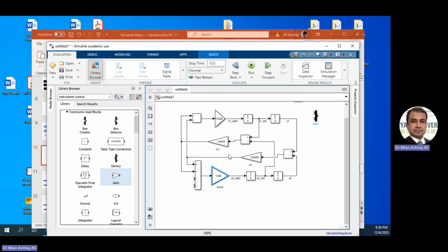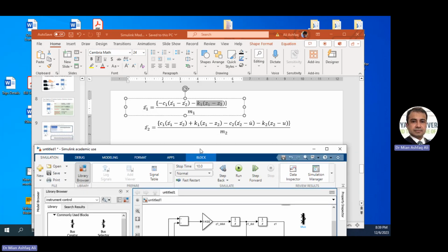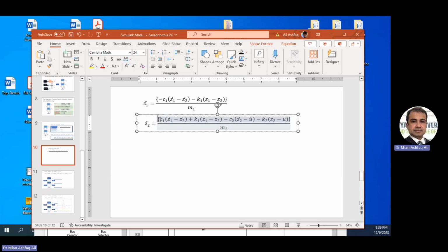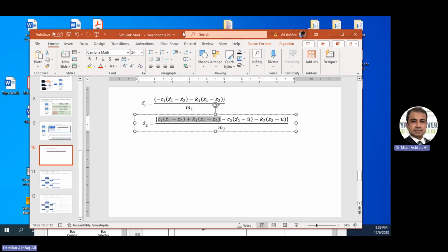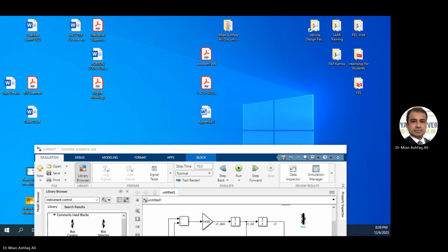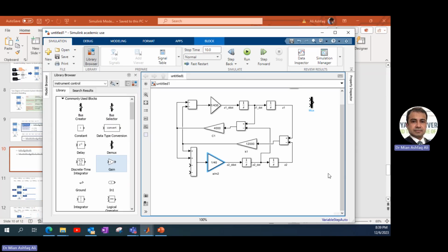And then those two signals are actually what? We can see from here, for Z2 dot, we have dealt with the first two terms, this term and this term. They are already done because they were readily available from the previous equation. We also need to know how to evaluate this one. So C2 should be negative, and it's the difference between the road velocity, the road profile velocity, and the input velocity. This means that I can simply have a road profile parameter.